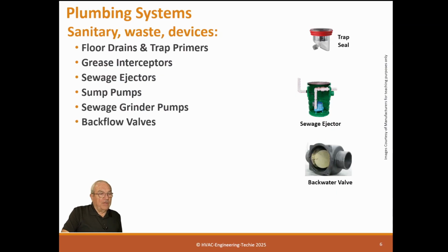And then we have backwater valves. The backwater valves go on the main sewer exiting the building. This is in case the building is situated such that if a sewer clog happens downstream of your building and backs up into the manholes, it's not allowed to come into your building. If your building is much higher than a manhole cover, you don't need them, but you would need them if your building is lower than the top of the manhole cover.